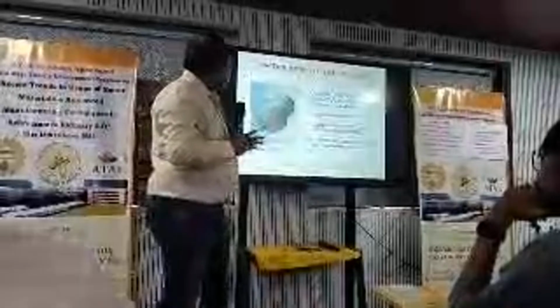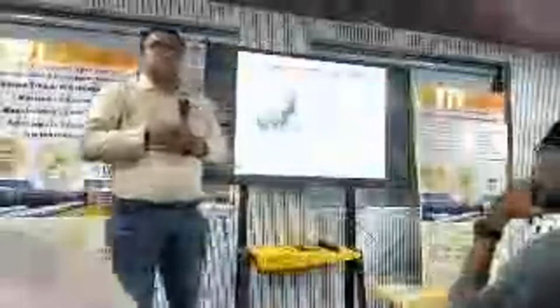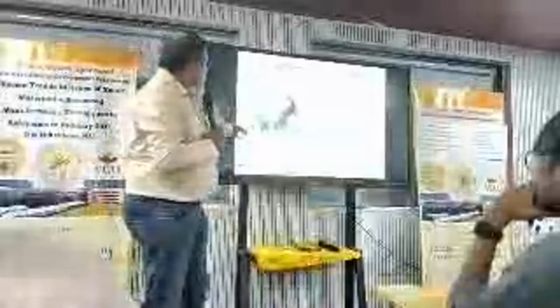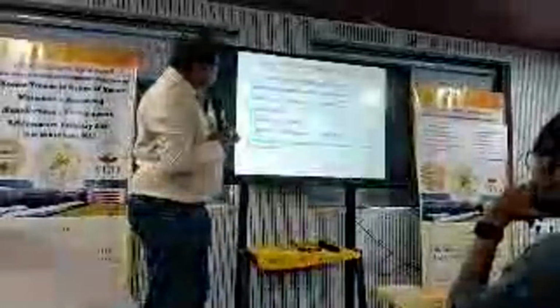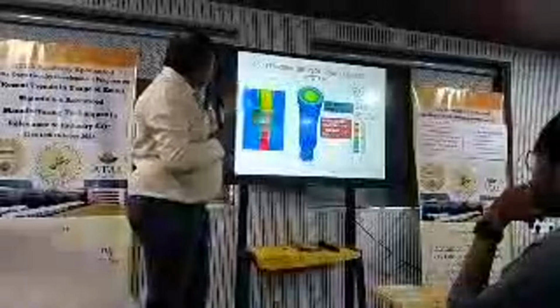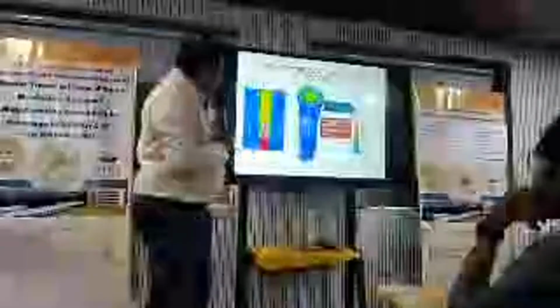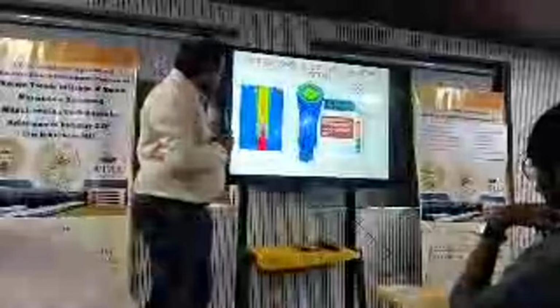There are some water injection techniques also. When the gas is flowing from the mixing tube, you have to inject some water vapor from the bottom, so that both the temperature as well as sound will be reduced. These are the water injection system measures. And this is the CFD analysis of the temperature across the fluid with the water injection system, before and after, how much temperature is reduced.